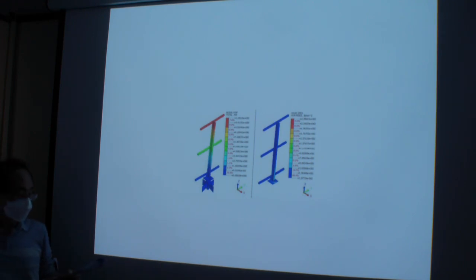Structural analysis was performed when the wind pressure acting on the soundproof wall in the normal direction was 735.54 Newton per meter square. The height of the soundproof wall was 6 meters. The H-beam spacing was 2.5 meters.